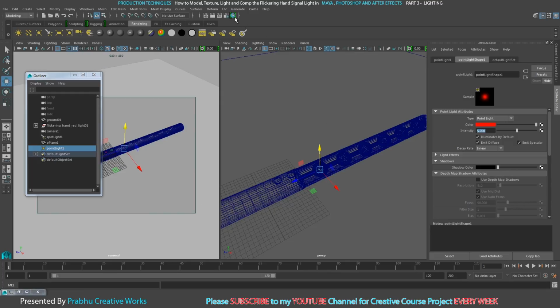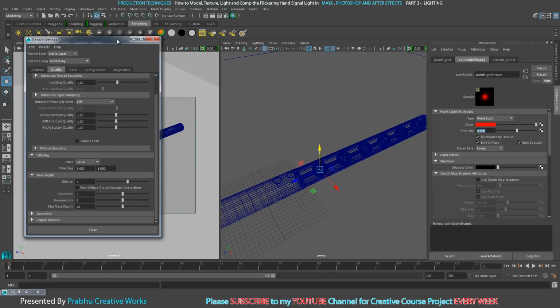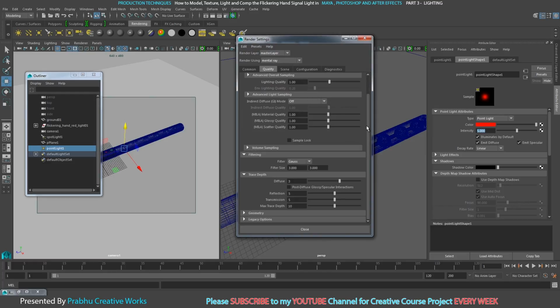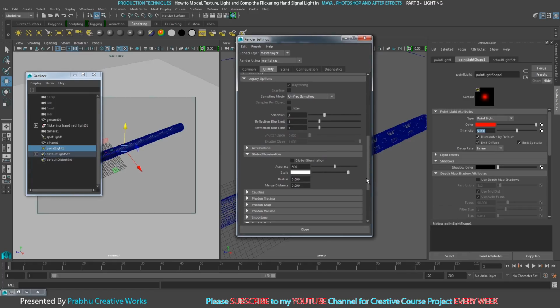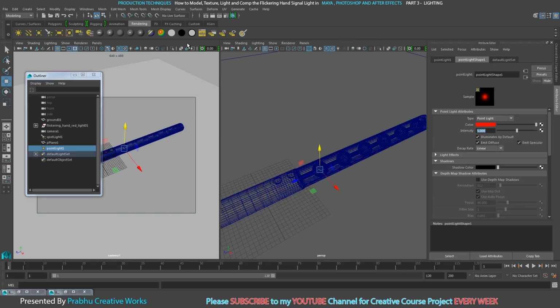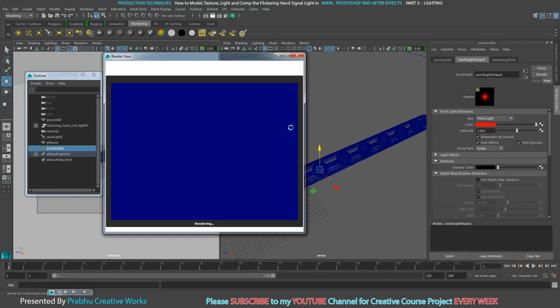final gathering. So go to render settings and configuration, in quality, go downside. You enable this legacy options, go downside over here. Here you have final gathering, so turn it on, and then you want to give secondary diffuse bounce to 1. So now check your scene, click render button.